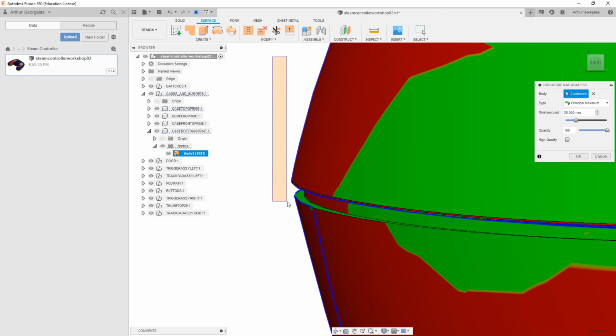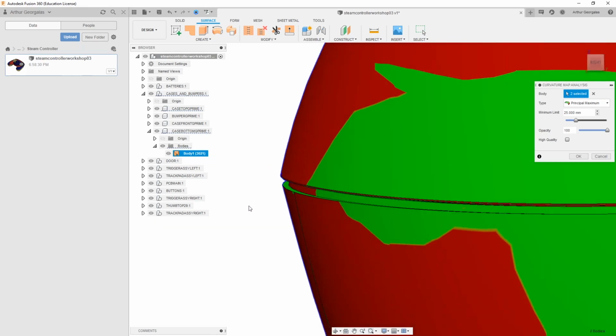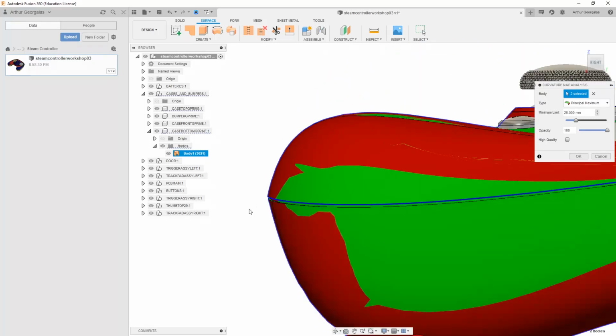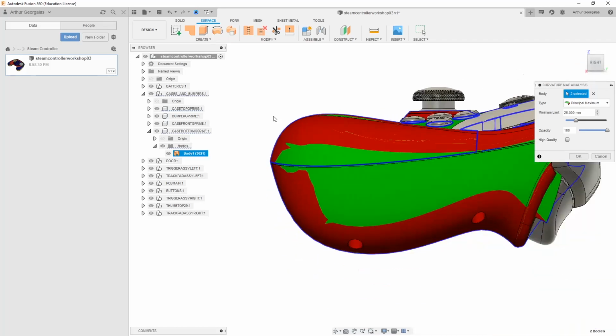That's kind of what's called a draft angle. So if any of these elements were poking out here, you would have problems with overmolding and your part would get trapped in the injection mold it's made in. We can go over that when we're actually modifying our parts a bit more, but it's important to note that generally you want to approach the part line and then move away from the part line with like a vertical line between them.